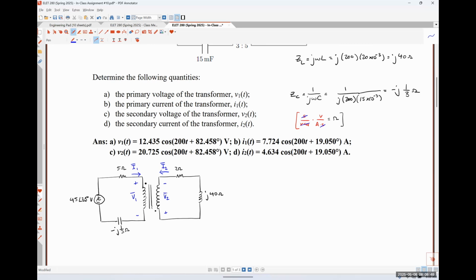So there are a couple of simplifications that we could potentially make to this circuit to make our life a bit easier, okay? So the first thing that we could do is lump those impedances together on the primary side and the secondary side, and just have a generic impedance that has both a real and imaginary part instead of treating it like two elements, okay?